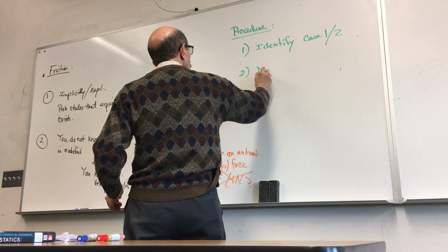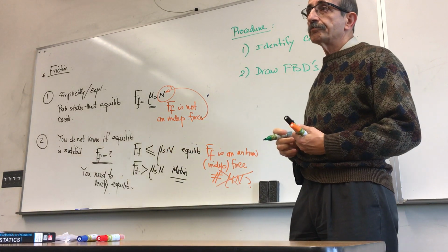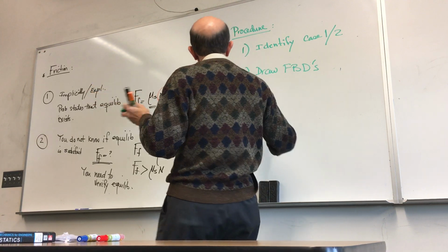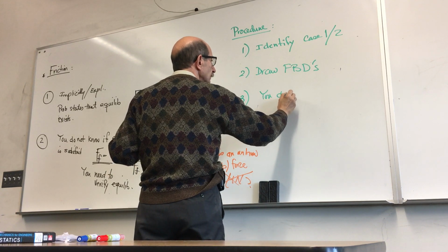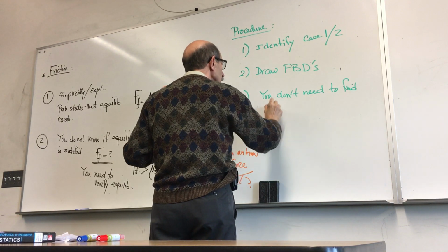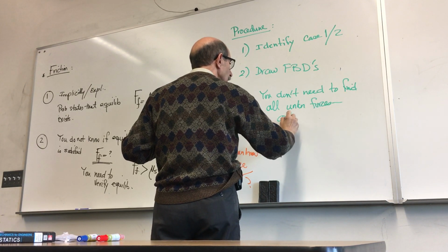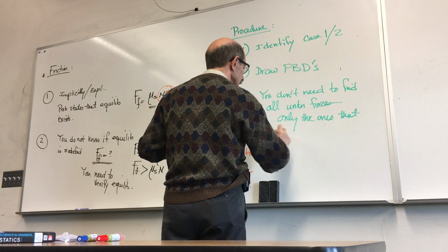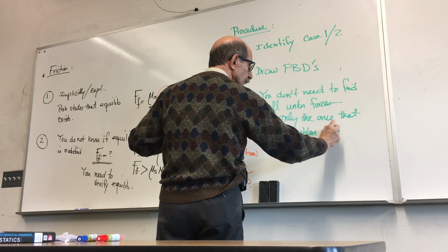You draw free body diagrams, okay? That's very similar to the frame problem. The only difference is that you do not need to find all unknown forces, only the one that the problem states or wants you to find.